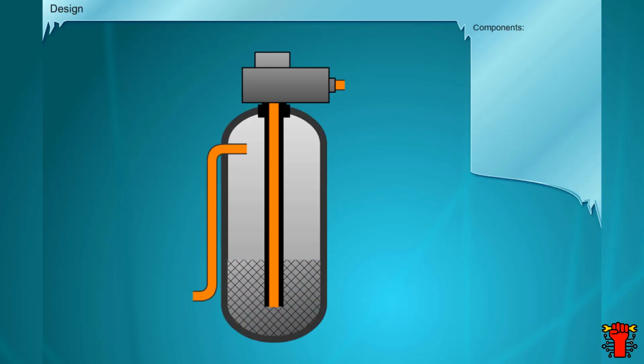In principle, the setup is similar for all fluid reservoirs. Essentially, it is a compression-resistant container. The opening is connected to the condenser via a supply line. A hygroscopic filter medium is embedded in the lower section. An ascending pipe leads to a second connection. This is where a line connects the reservoir to the expansion valve.